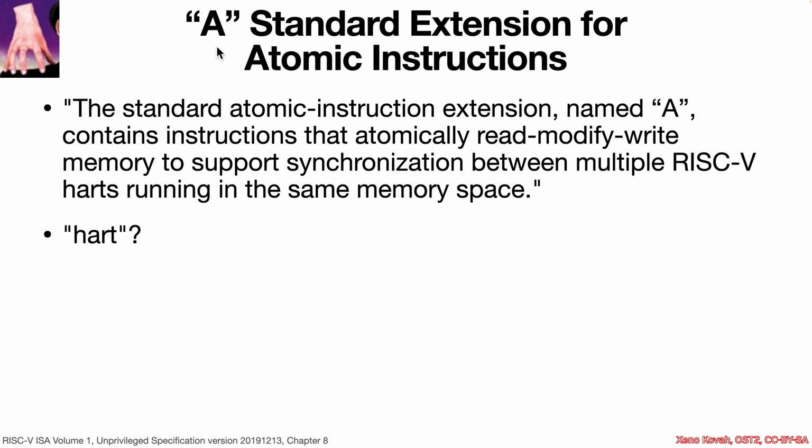Then we have A for atomic instructions. The standard atomic instruction extension, named A, contains instructions that atomically read, modify, and write memory to support synchronization between multiple RISC-V harts running in the same memory space.